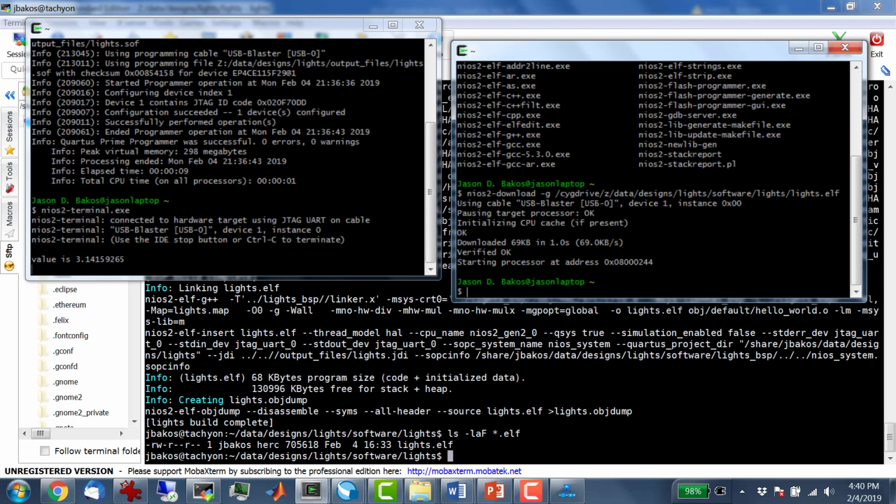So the first thing I would have done, had it not printed, is go into GDB and debug to make sure that the program I thought was running was getting to the line that said to print. You guys with me? If that worked, then I would have investigated why the UART wasn't working, right? Because I would have known that the hardware was good, the FPGA was configured, the ELF file was downloading, and obviously it was getting into memory because the download does a verify too. And then the code was running, I could debug it gets to the print, so it was just a problem with the UART, so I would have drilled down to the UART.